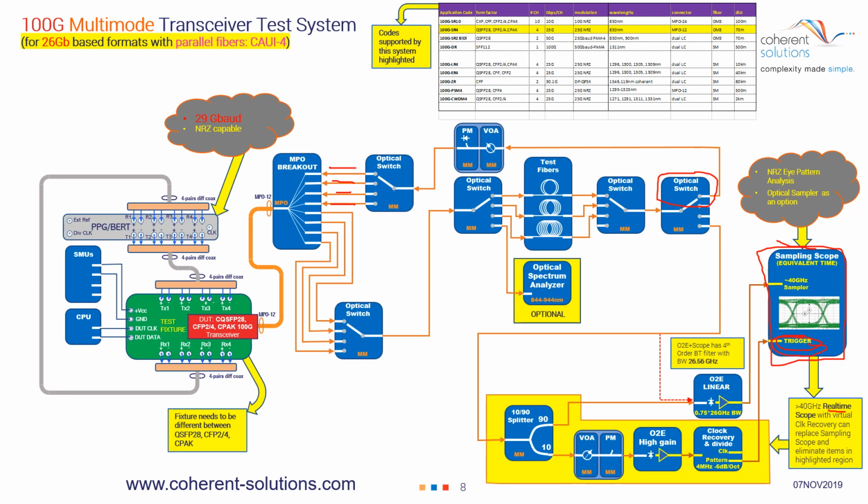Now, many users may ask, why not use the trigger from the clock of the original transmit signal, which is over here? And in some cases, that is fine. However, once you start transmitting signals through longer lengths of fiber, you will notice that the inherent drift in the trigger signal relative to the actual waveform you want to measure becomes unacceptable.